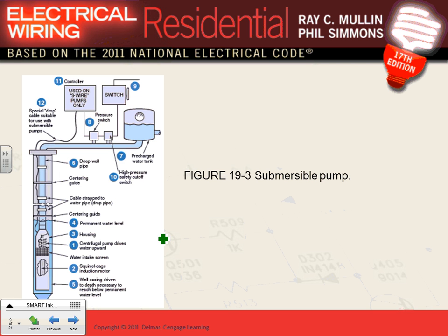So the two technologies: the jet well, where you put the pump itself above the well, and the most common one, the submersible pump. Can you guys see where they put the pump right in here with the impeller? What's our involvement? I always like to start with our involvement. Our involvement is the overcurrent protection device we have to provide. So here's number one. Number two, I need a disconnect.